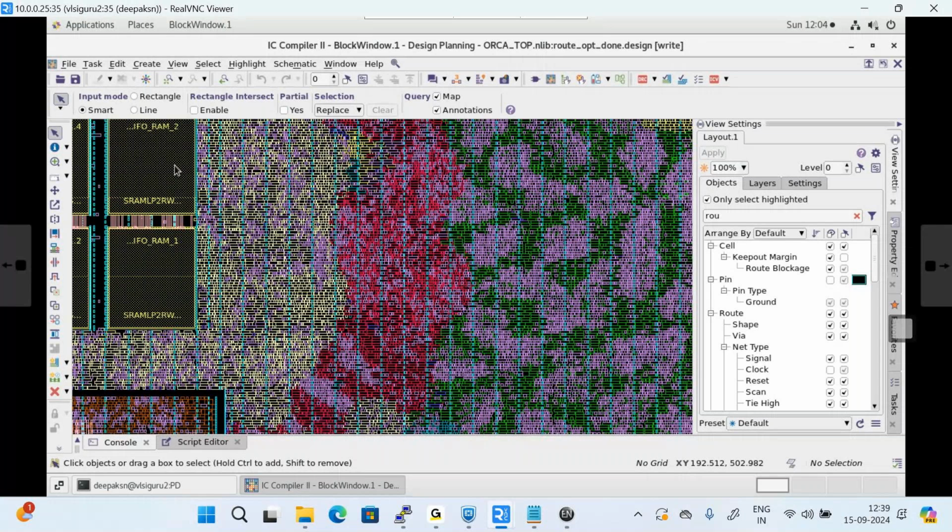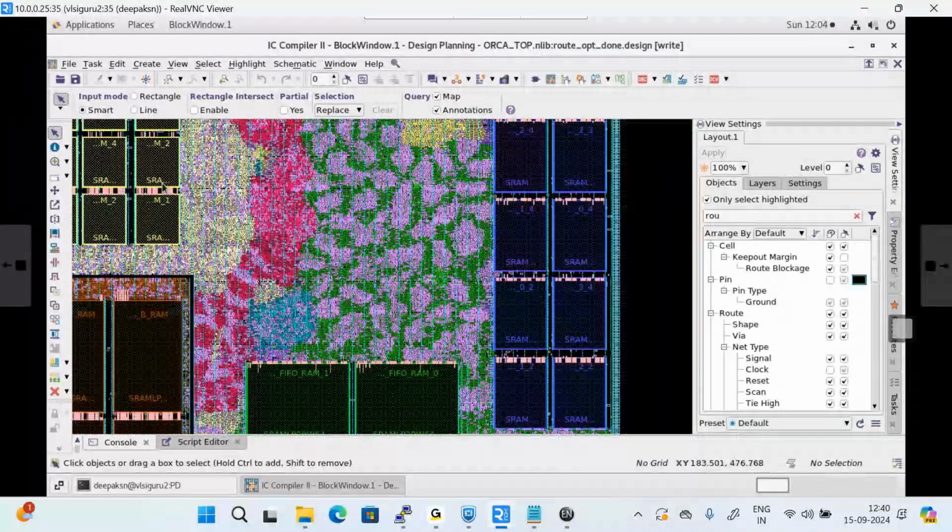we take the GDS file from that team and we take the LEF file. We incorporate them in our physical design. So in physical design, we have even files from them. I am not designing the PLL. As I'm using a macro here, I will reuse the PLL that they have generated. Oh, okay.